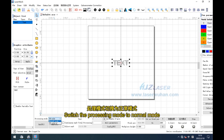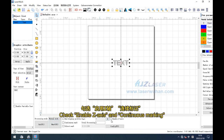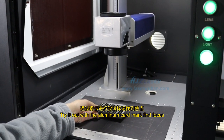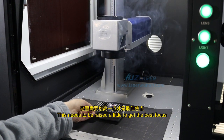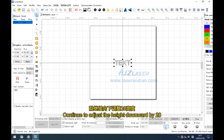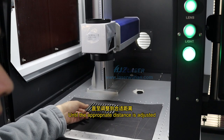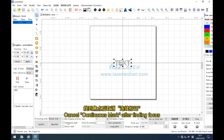Switch the processing mode to normal mode. Check Enable Z-axis and continuous marking. Try it out with the aluminum card marks to find focus. This needs to be raised a little to get the best focus. Continue to adjust the height downward by 20 until the appropriate distance is adjusted. Cancel continuous mark after finding focus.